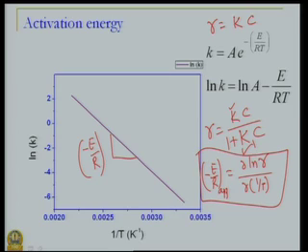So, when it comes to making some judgment whether processes are transport related or transport controlled or kinetically controlled, a good rule of thumb is to look at the activation energies. Activation energies typically 40 kilocalories per mole to 100 kilocalories per mole are typical of any chemical reaction. But if values are much lower than that, that indicates that it is not the kinetics, but something else that may be controlling the process.